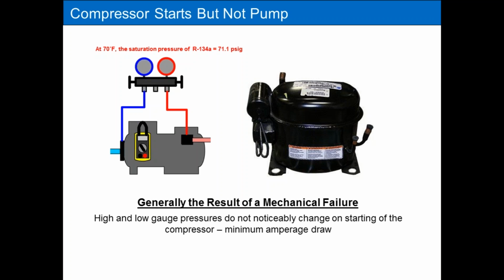Low side pressure drop. Typically it's going to drop into a vacuum or very low, and your high side pressure is going to go up a little bit, but maybe not a whole lot. So that tells me that the compressor does pump, hopefully well enough to keep working, but at least it pumps, and my major issue at this point is just loss of refrigerant, which means I have a leak somewhere and I've got to find the leak.